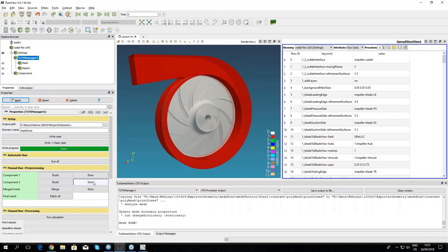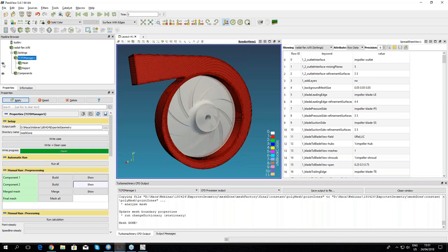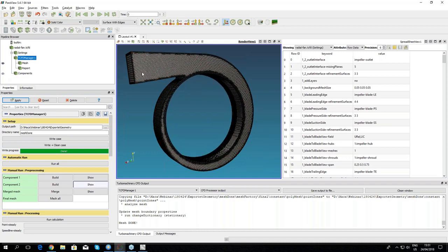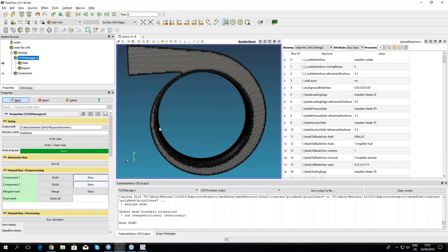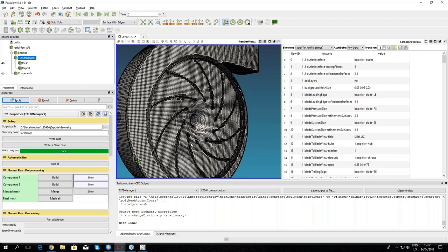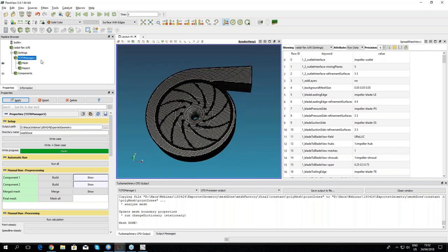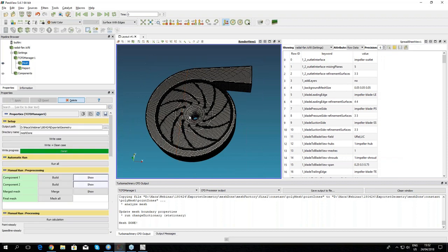Anytime I can visualize each part of my design. Okay, so I can click here into this render view. I can just visualize the mesh. Yes, and here you can investigate how the mesh looks. And I can add, for example, the rotor part, and investigate if the mesh looks okay. I can perform anything you want, for example, some slices through your geometry and so on, just to see how the mesh looks inside.